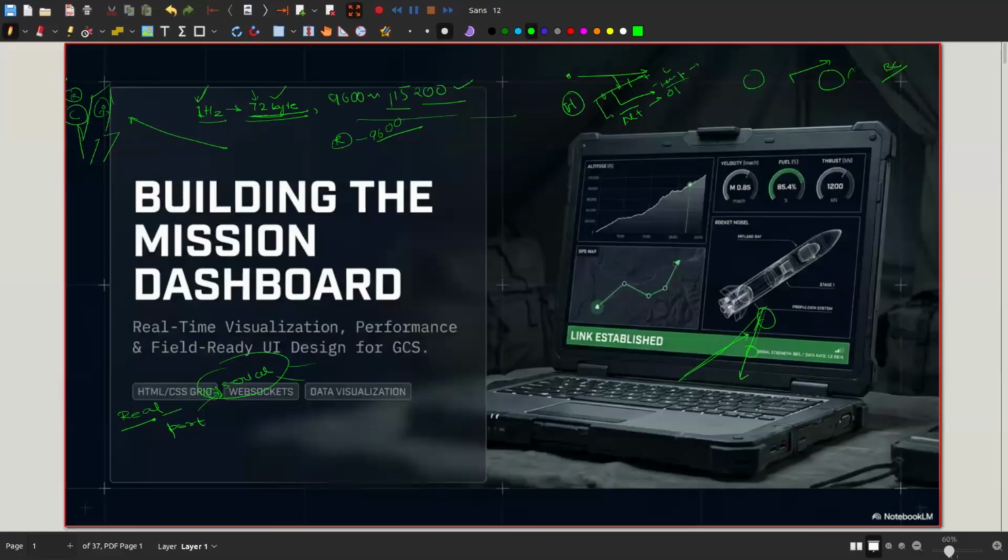First, you have to create an instance. You have to create something that receives your data. So how will you receive your data in the backend? You use the PySerial library. It looks out for the different ports. Let's say you have USB ports in your laptop, probably two or more. My laptop is old, so I have two ports. These are your USB port 1 and 2, and they are named differently by your operating system.